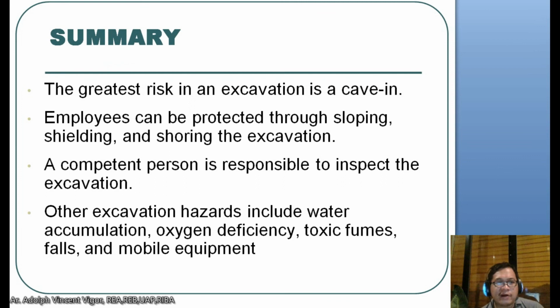So for our summary, the greatest risk in an excavation is a cave-in. Employees can be protected through sloping, shielding, and shoring the excavation. The competent person is responsible for inspecting the excavation, and other excavation hazards include water accumulation, oxygen deficiency, toxic fumes, falls, and mobile equipment.